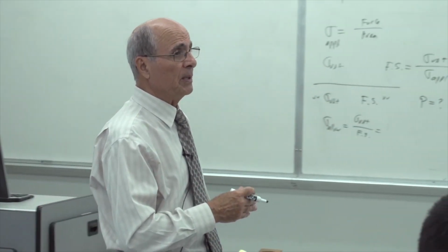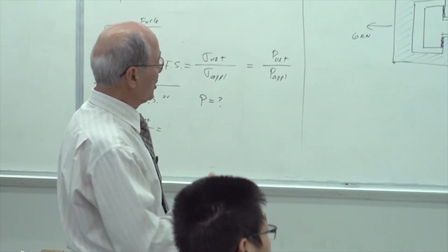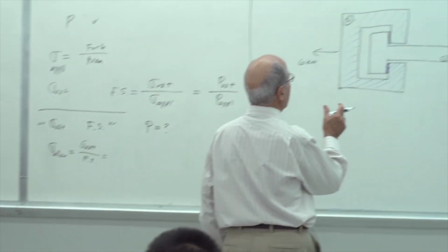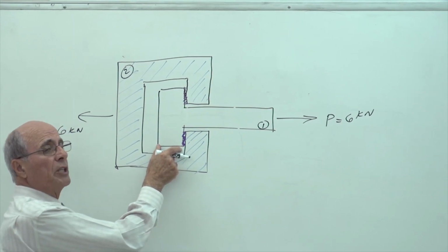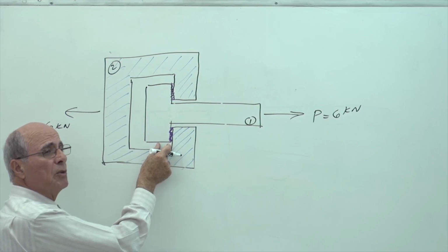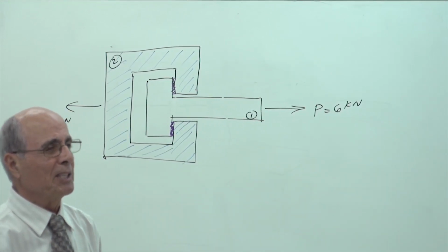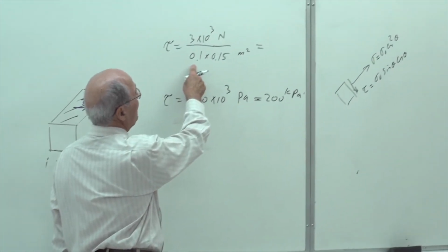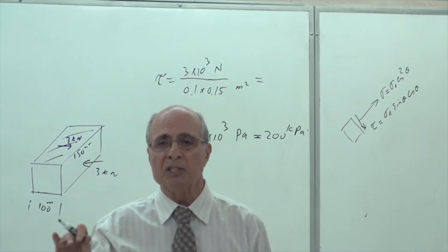Is there another way of damaging this structure? Yes, that's line BB. If this is not thick enough, 100 millimeter is about 4 inches. So if you're making a piece of wood 1 inch thick, it easily is going to shear off. Everybody understand what I'm saying? Here I use 4 inches as 0.1. If this is 1/4 of that, the stress becomes 4 times more. So easily you damage it going through that.